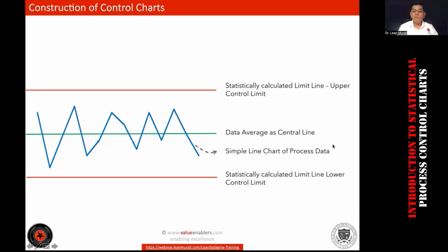So all of you type UCL and LCL. UCL is the upper control limit and LCL is the lower control limit. Also you can write CL, which is the center line, and average. Center line and average may not always be the same line. The average might shift from the center line many times. Our objective is to make sure the average overlaps the center line, but in most cases, since the process drifts and shifts, it may not be on the center line.